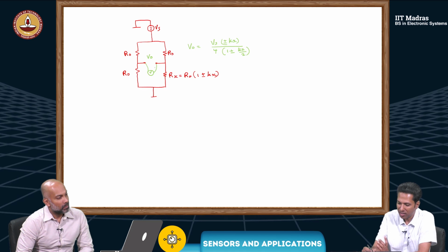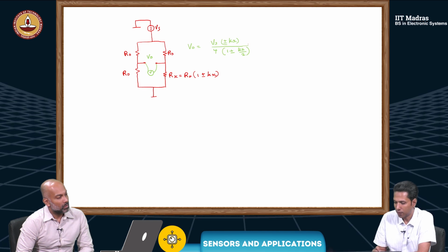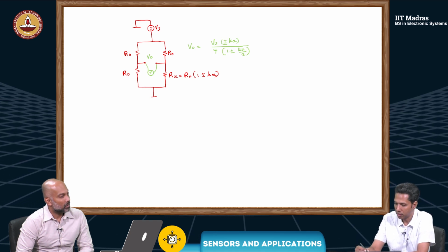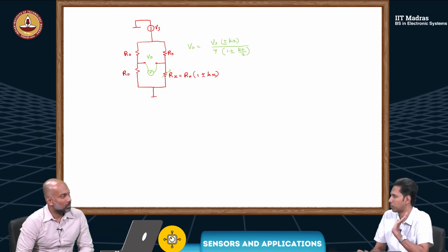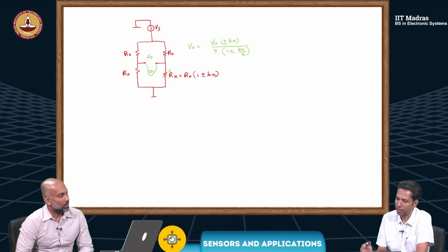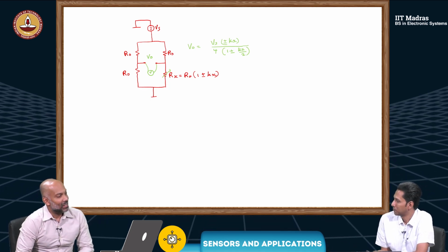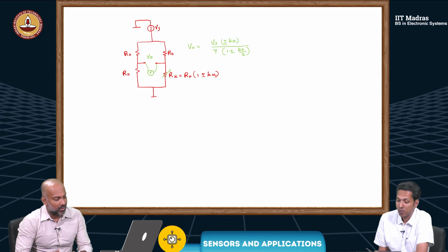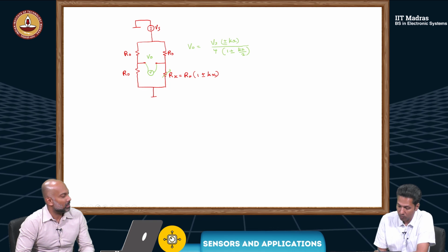So I was thinking, what is wrong? This equation we derived for open circuit voltage. The bridge was open, and then the Rx changed due to the strain or temperature or some parameter. I was expecting, let's say, X millivolt. I got maybe 0.8 X millivolt, 80%. So the only thing I can think of is there is something else that's drawing a voltage, and if that's the case, there must be some sort of resistance.